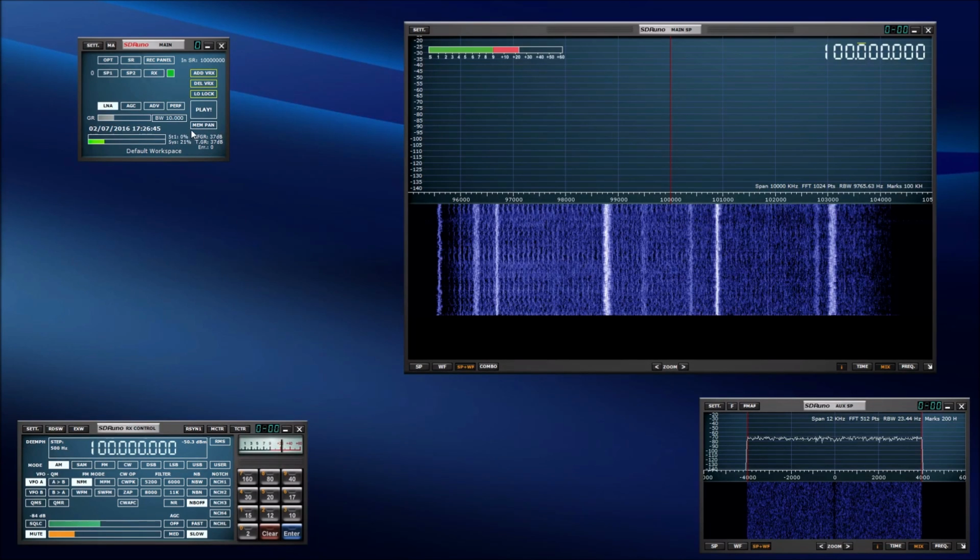So the simple way is you just specify the bandwidth that you want to be working with in here. So I just click in here, and I say, I don't know, 5 megahertz, and I want to play with 5 megahertz of bandwidth, and you decide whether you want the LNA on or off. This GR slider under here is gain reduction.